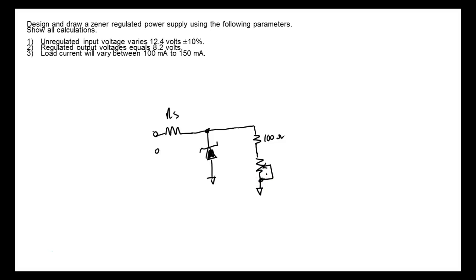Now, what's nice about using a 100 ohm resistor is that we can measure the voltage across it. We can use the 100 ohm resistor as a shunt, right? You understand that? Which means we can measure the voltage across the 100 ohm and calculate the what? The current. So if I measure 3 volts and I divide that by 100, what's that going to be?